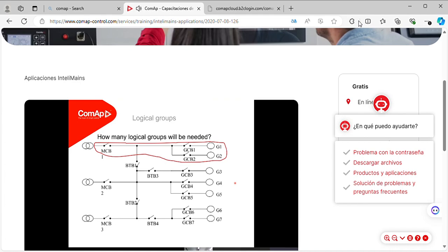Basically, if the bus tiebreaker 1 is open and the grid fails, the gensets will start feeding the load. If the grid is back, G1 and G2 can synchronize back to the grid and work independently. Then the second grouping is this individual genset. If you close GCB3 and start generator 3, it can go to the common bus here, and it can also feed a load on this common bus upon the bus tiebreaker control. Or if there is a load on this bus, it can feed the load individually. So this is the second group of genset.